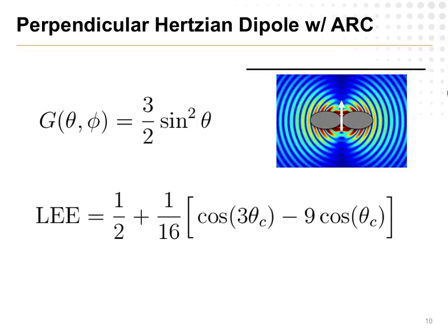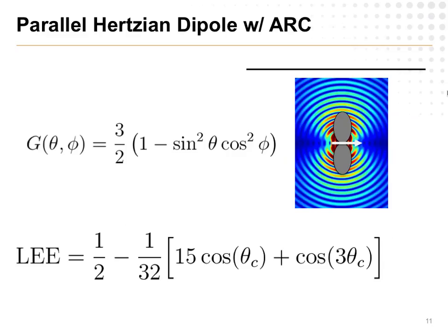So you can calculate in advance the absolute best light extraction efficiency I can expect, assuming my recombination event has some preferential direction to it. And then you can say, well, what if it's actually the other way? Because that could work for you rather than against you, right?